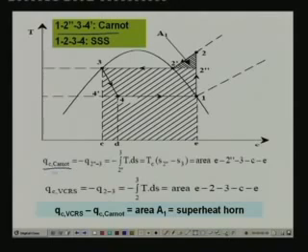And what is the heat rejection in the Carnot cycle? Heat rejection in the Carnot cycle is nothing but heat rejected during process 2 dash to 3, that is nothing but the area under 2 dash to 3, which is equal to Tc into (S2 dash minus S3), that means this entire area. Okay, that is area E2 dash 3 CE.